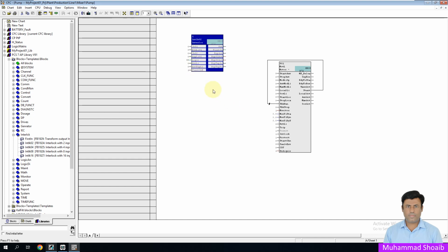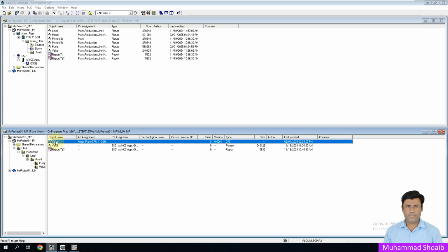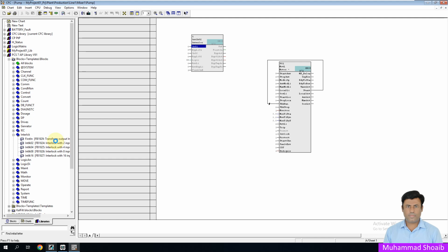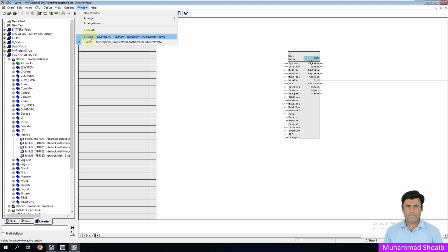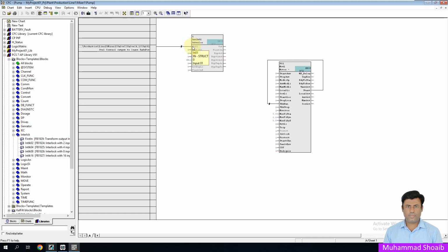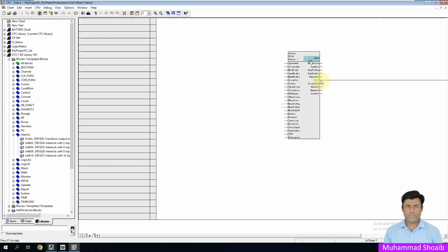Okay, so first I will select here my first input. I will link my control valve like in the previous tutorial where we already created the CFC chart. I will open the same, and the output of my CFC chart I will connect with the COM1. So as you can see, select this one and click it here, it will automatically link.